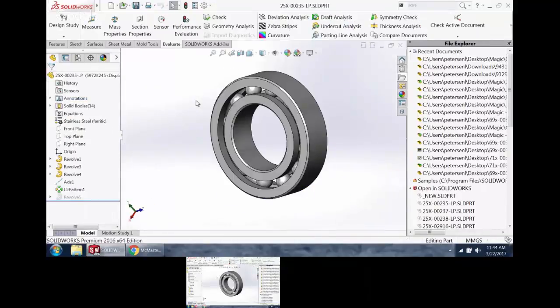So there are balls in that ball bearing. We don't really need that much detail in the ball bearings. It's not going to really hurt me graphically when I'm looking at the entire assembly because the bearing's inside of the motor casing. But if I go to wireframe or hidden line shade, it's got to draw every one of those balls as I'm rotating it. And if I've got 15, 16 bearings in there, then I'm screwed as far as how this thing starts to react.